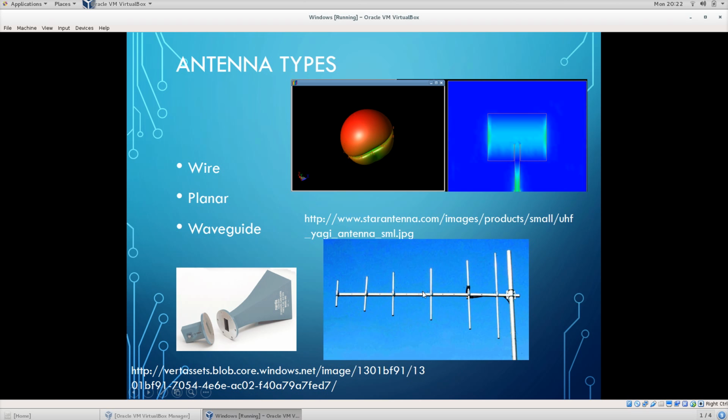That's why these are common antennas that you might see for, like, your TV, especially since they're, again, very easy to construct. Now your TV antenna might look a little different because it might have a bunch of different sizes and shapes around it, but effectively it's just because it's trying to be able to tune to more than one frequency. Most types of antennas like this rely very heavily on the frequency of operation, which determines very thoroughly what the dimensions of the structure are. And because of that, they tend to be fairly narrowband unless you do some interesting things.